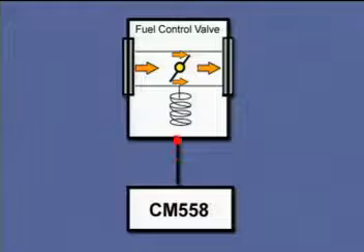The fuel control valve is driven by a 24-volt pulse-width modulated signal that comes from the left bank CM558. This butterfly-type valve controls the amount of gas entering the engine for any given condition.